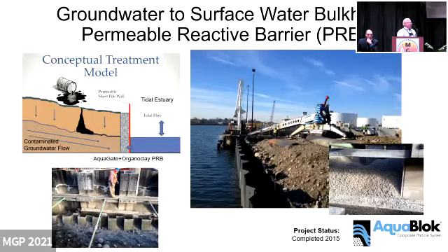application. You can see here that this was a petroleum related facility where you had, this is kind of the CSM, the contaminated material that was in the subsurface. There's a sheet pile wall that has to remain permeable because they didn't want to create an issue with mounding of groundwater behind the sheet pile wall.